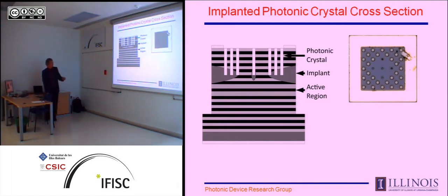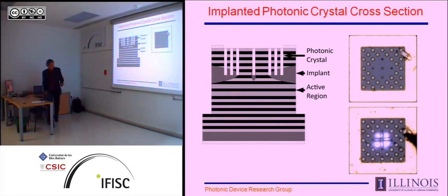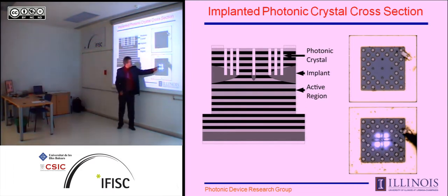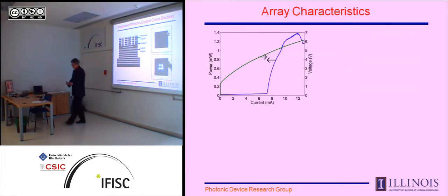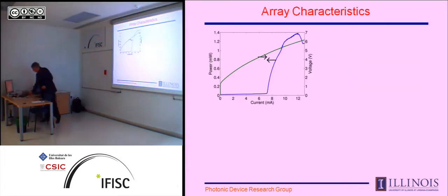And so this is what it looks like from the top. And you can just make out there's a couple of holes here which define the array. When we fire up and put current in that, then we get this 2x2 array. And what you'll notice is that there are these fringing fields between the elements. That is a sign of coherence, that we're actually coupling between these elements and giving us a coherent array. And the result is, in the far field, we see an in-phase mode.